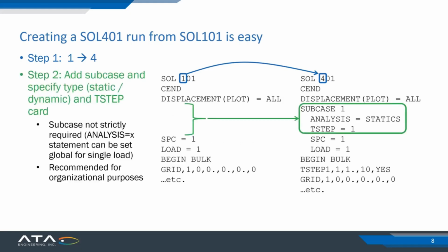The next step is that you're going to add a subcase with a callout for the analysis type of that subcase. And that is not strictly necessary in terms of adding the subcase, because you can just do the analysis equals whatever statement for the global load set. But I recommend starting it with a subcase in case you want to add further subcases later.